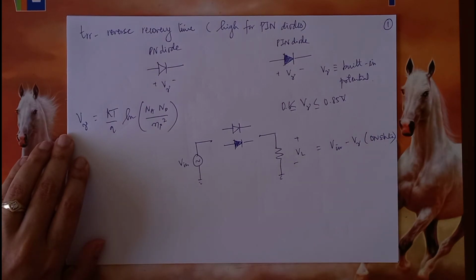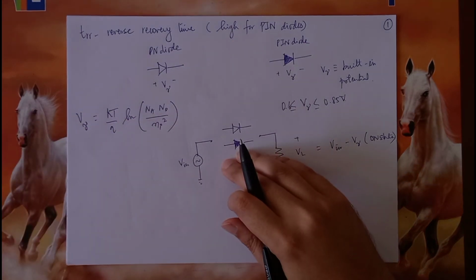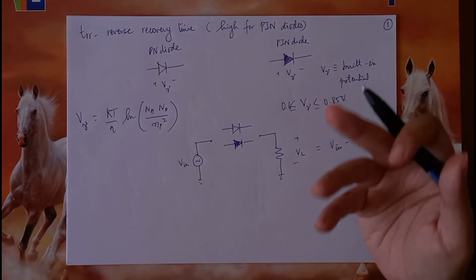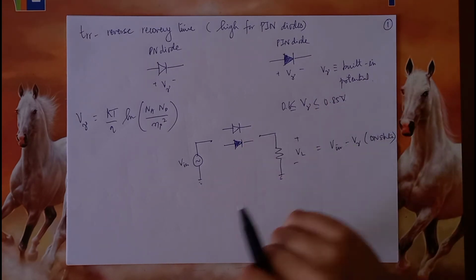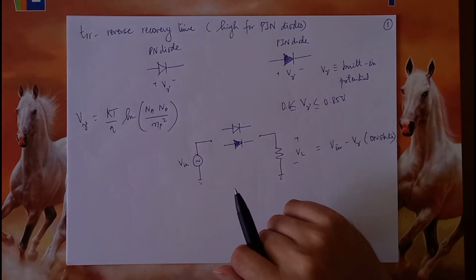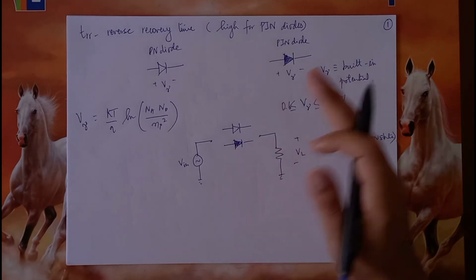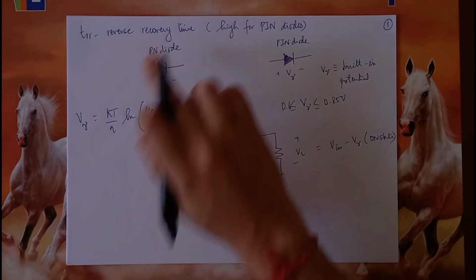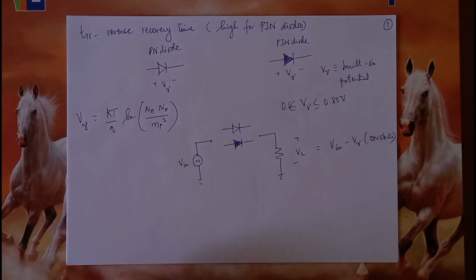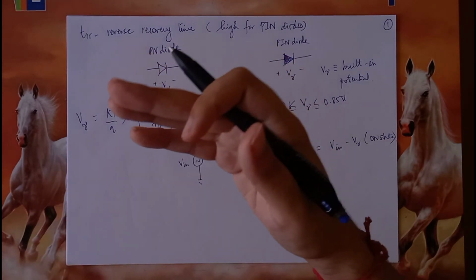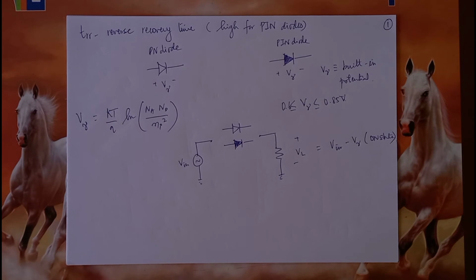One of the semiconductor materials which can be used to make diodes and can also offer a lower built-in potential is germanium. But essentially germanium again suffers from the same problem as the PN diode. That is, the germanium diodes that are available are usually quite poor insulators when in reverse bias.